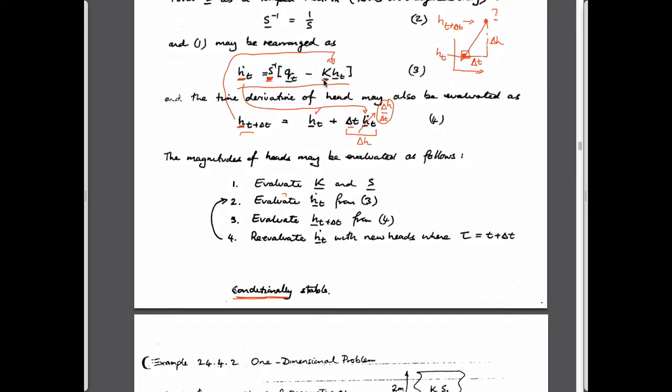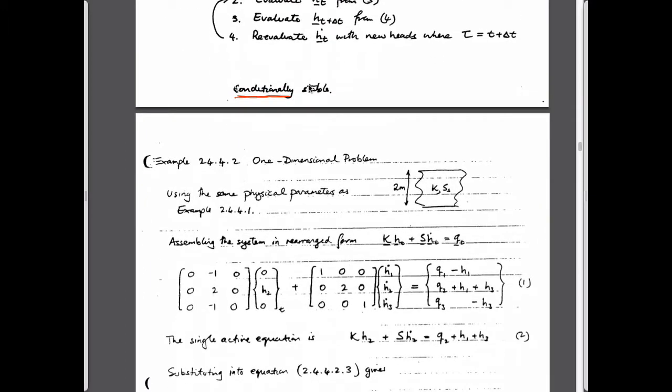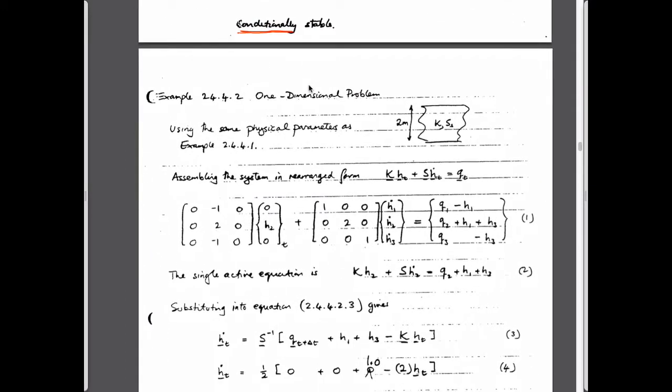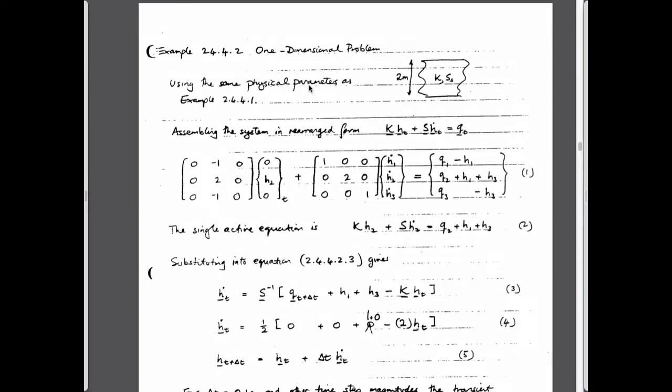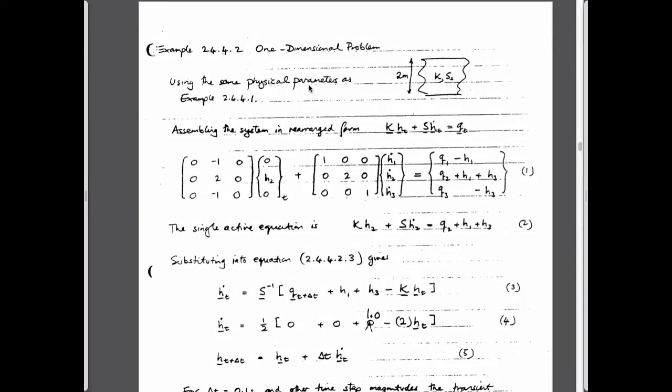Changing the conductance matrix is a bit problematic. But if you're solving the system anyway, having to use time steps to follow maybe nonlinearities in the behavior, then there's no real problem in using an explicit method, because it's actually cheaper to solve than using implicit. Okay.